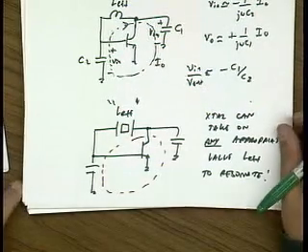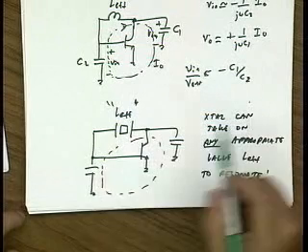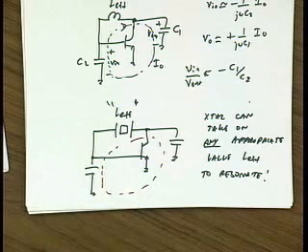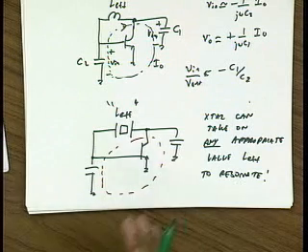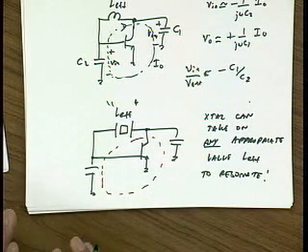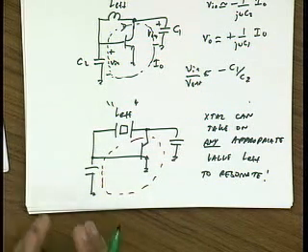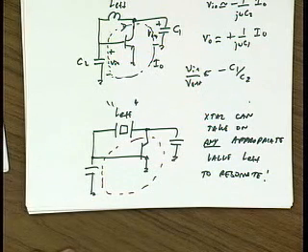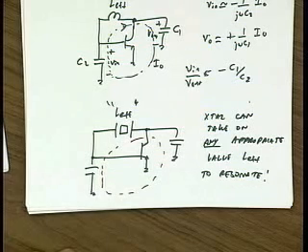Now this would not be useful because at this point we don't know what frequency it's going to resonate at. It's going to be some frequency between omega s and omega p. But as I'll show you in a couple of slides, those frequencies are extremely close together. The series resonance and parallel resonance are almost right on top of each other. So in a very small, narrow range of frequencies, I can make this circuit oscillate, and so it's a very predictable frequency of oscillation. But then I can use the capacitors to tune it, a bit.